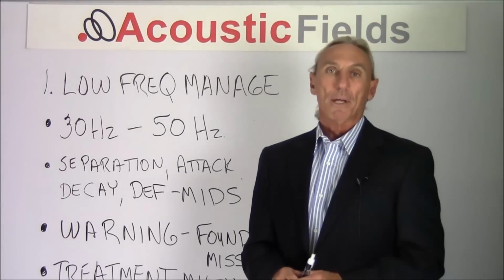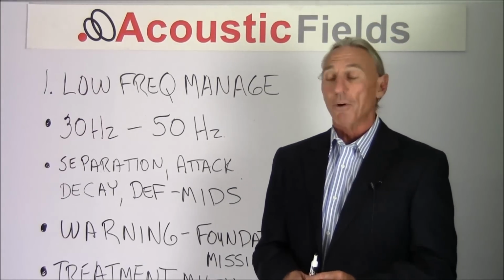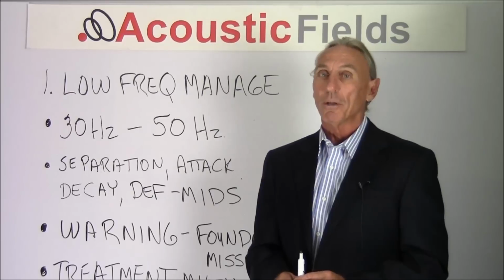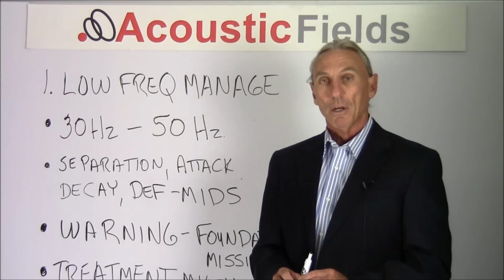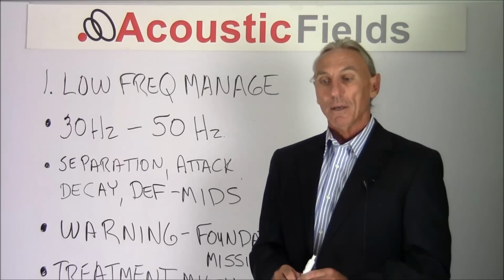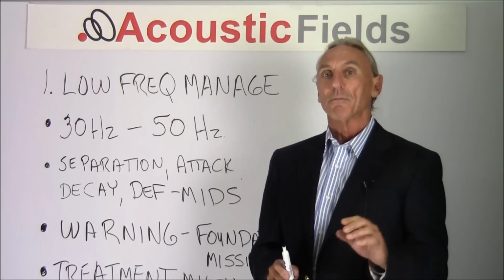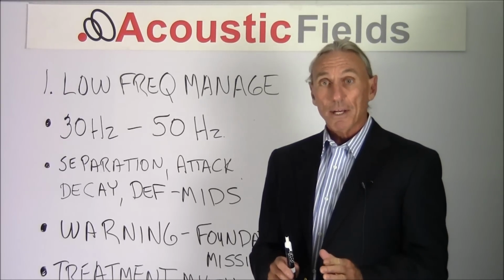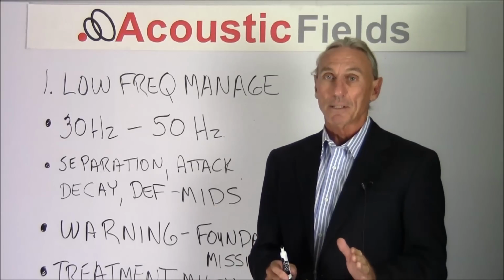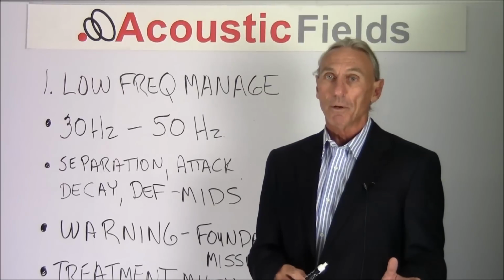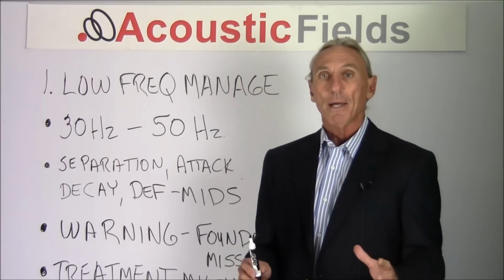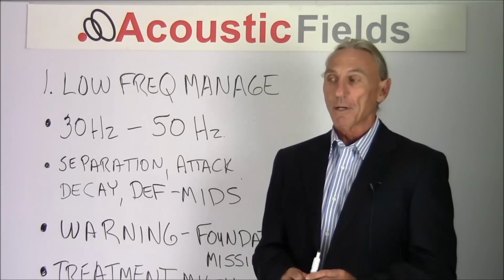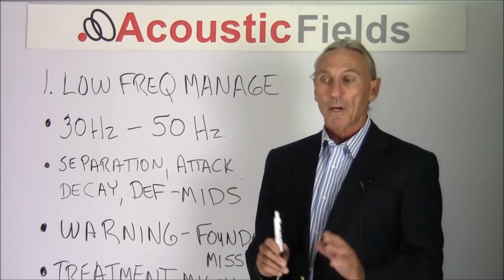Treatment myths, be very, very careful. Boxes filled with building insulation foam are not low-frequency absorbers, at least not in our definition, which is all energy in a small room below 100 cycles. We use that as our dividing point because different treatment technologies are necessary for below 100 hertz and for above 100 hertz, and you can't mix them. They're not all-inclusive. One works one way, one works the other way. You can combine the two technologies, but saying that foam and boxes filled with building insulation are low-frequency absorbers does